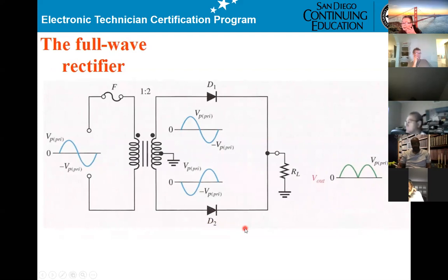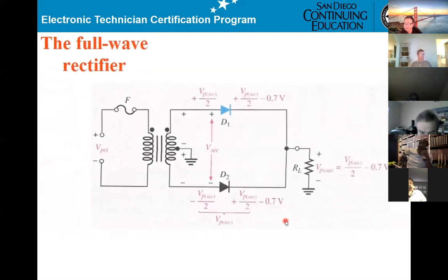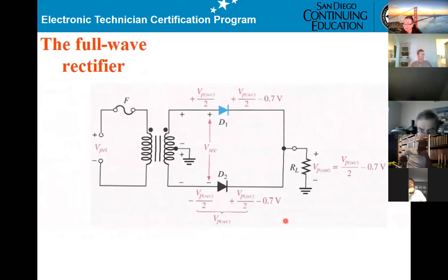Okay, so in here they just try to give another one with 1 and 2, and you get the voltage here. Output will be minus 0.7. We also have an increase in frequency, right? Double the frequency on the output. Input 1 kilohertz, output 2 kilohertz.